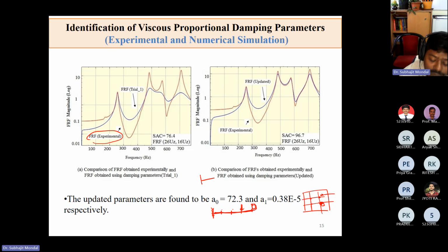Now, an accelerometer can be of two types. One is the 1D accelerometer. If you go for real-life testing, you should also make sure what the type of accelerometer is. A 1D accelerometer means it can do one-directional measurement. So how we place the accelerometer also matters. For example, if you have an accelerometer that can measure only in one direction, the vertical direction, then you should place it in the vertical direction only. You should not place it in any other way, otherwise your measurement will be wrong.